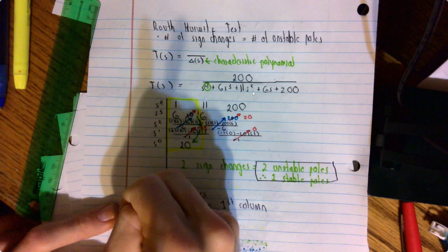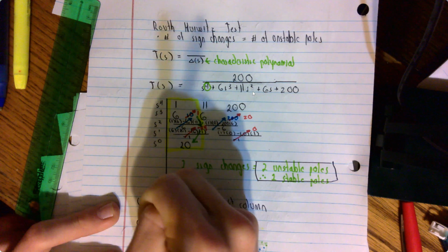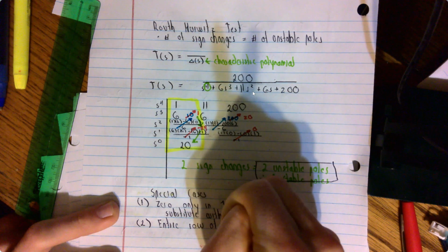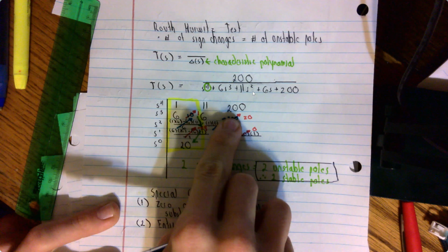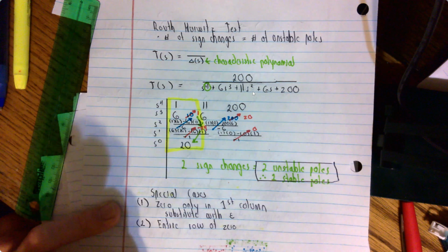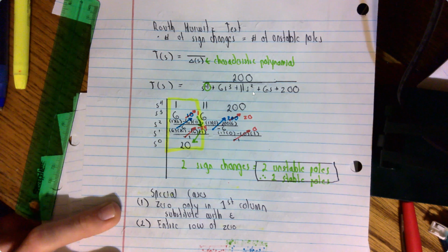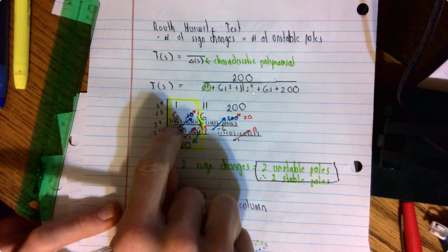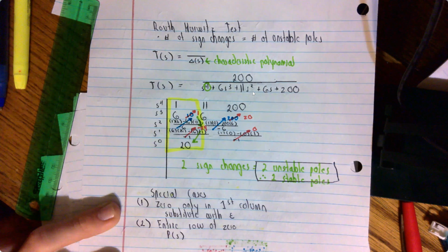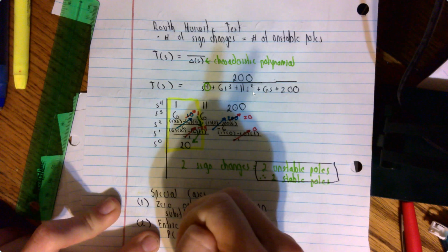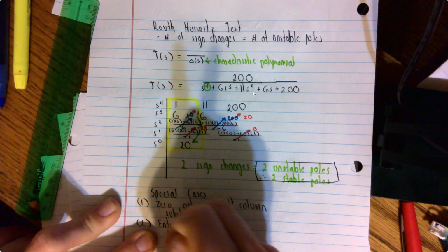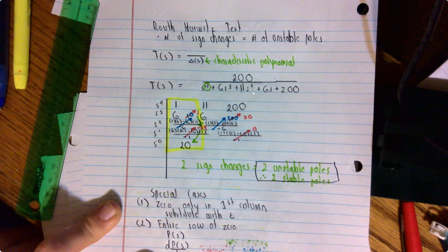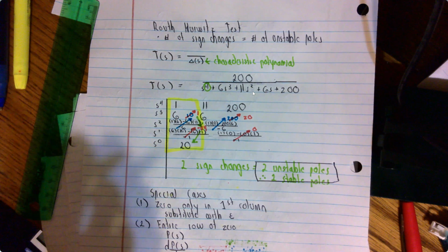And then case number 2 is that you have an entire row of zeros. So that would mean, say, what if this was 0, 0, 0? And so what you do is you have to look at the row before. So if we're looking at row 3 and it is all zeros, you look at row 2 and set that equal to P of S, and you take the derivative of it. Then you substitute that in now for your row 3. And so then that's how you would proceed with that one.